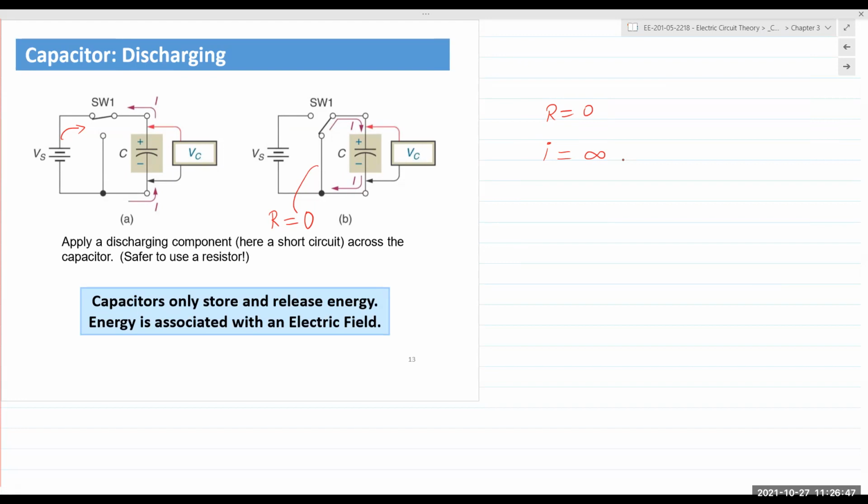Does anyone remember the Galaxy Note 7? That exploding smartphone that came out a few years ago. What the battery engineers were trying to do was make the batteries thinner and thinner and thinner. And so the separation between the cells of the battery was very, very thin. And that resulted in the battery cells being shorted out.